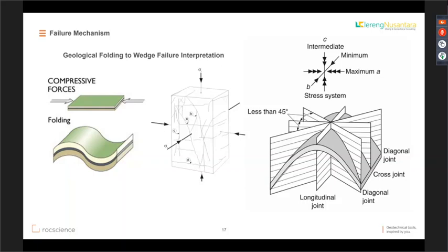The stress exists, in at least two different directions. And then if we open the lateral constraints by excavations, followed by mining activities and also blasting activities, stress relaxation happens. And when stress relaxation happens, the stress finally has a chance to manifest itself in a physical form as a discontinuity.